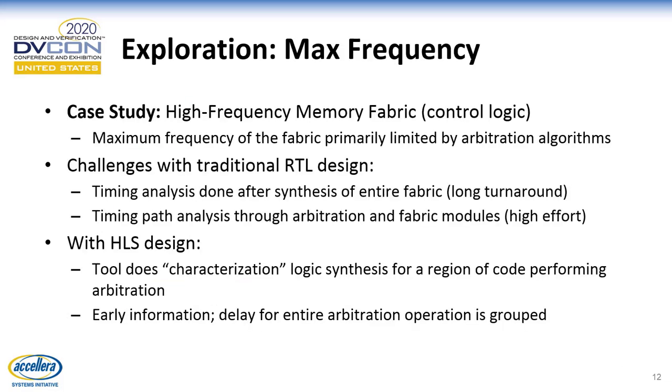The other case study I'll talk about is less in the algorithmic space. This is a high-frequency memory fabric, call it a crossbar router, whatever you like. This is mostly control logic, FIFOs, things like that. So this isn't one of the designs I can just ask the tool to pipeline and it says somewhere between 5 and 7 cycles. Often you want to say more exactly what you want here in these type of designs. But we still see some benefits with HLS.